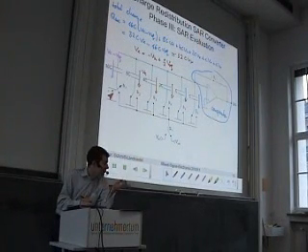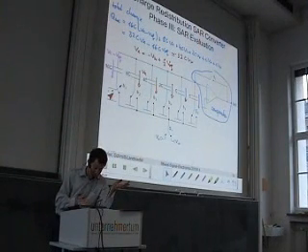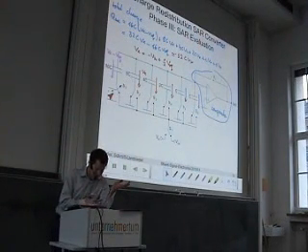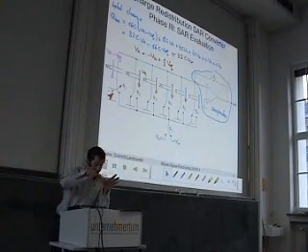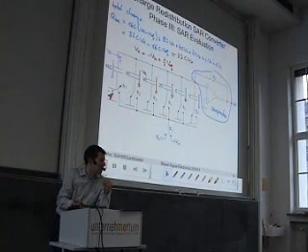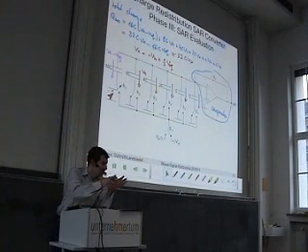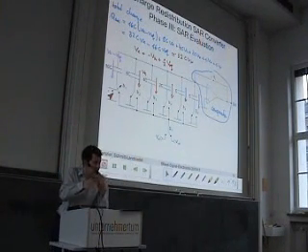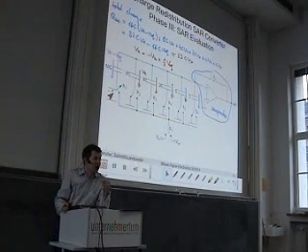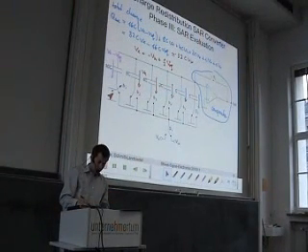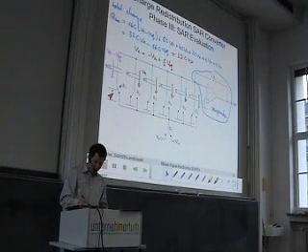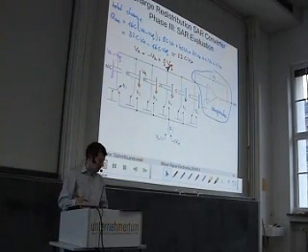And now it comes into play exactly what you said, that now, although the total charge is the same, we shift it between the caps. And this is the reason why we call this a charge redistribution architecture, because we move the charge from one cap to the other one, but the overall charge remains the same. Okay, so what we did here is to increment the internal voltage by Vref over 2 here, and then check for the sign.